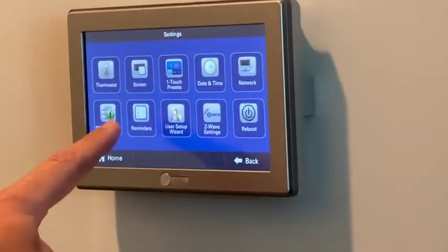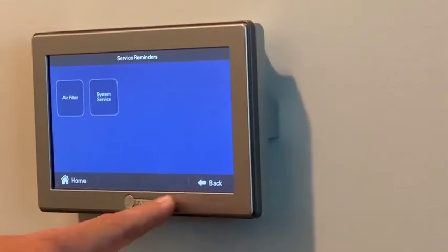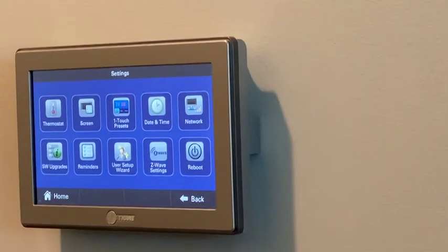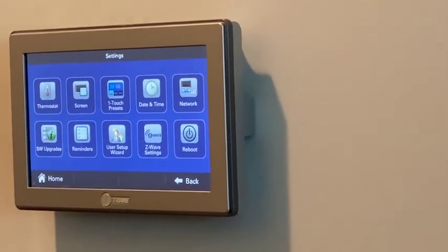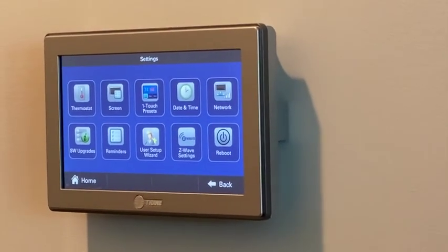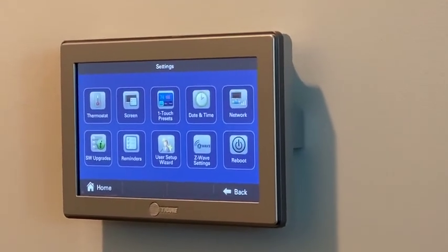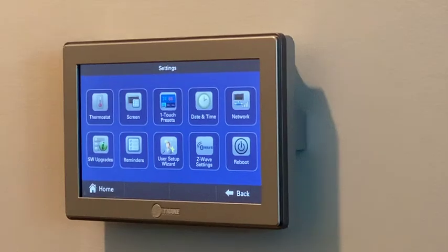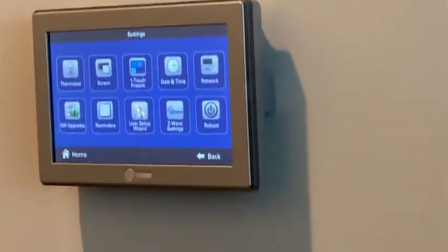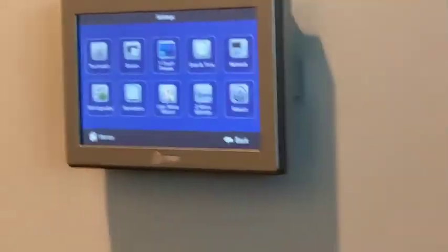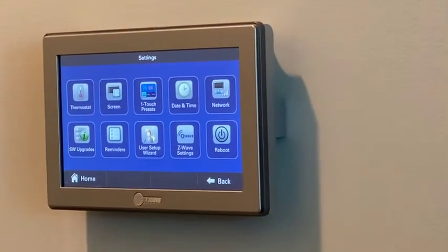So what about when people say you should not ever, when you come home and it's really hot out and it was cool this morning, put it more than 3 degrees at one time? Yeah, in the wintertime it's more prevalent than the summer. In the summer, if you're not home for a couple of days, you want to set the thermostat on about 80, and then when you come home, you can crank it down to 72 if you want. It won't hurt anything. Really? Yeah.